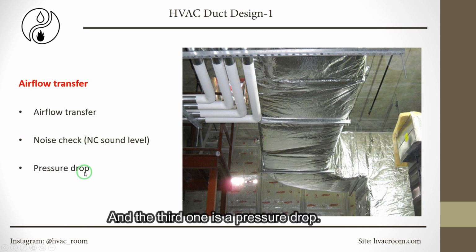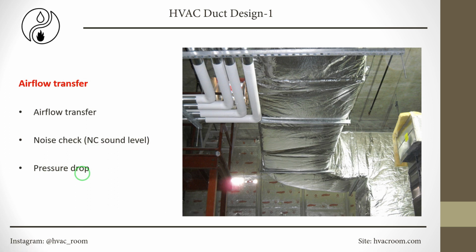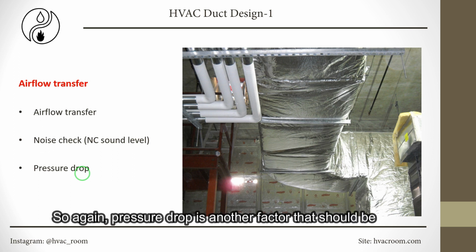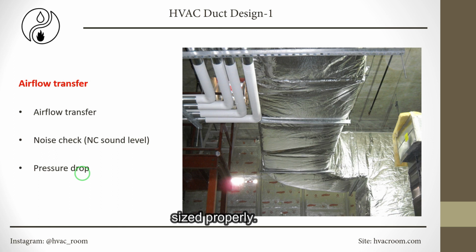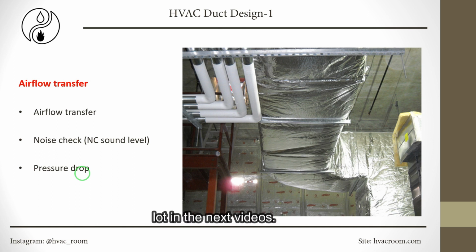And the third one is the pressure drop. Again, if the pressure drop is so high, it's going to increase your current cost. If it's so low, it's going to increase the duct size. So again, the pressure drop is another factor that should be sized properly. We're going to talk about these parameters and factors a lot in the next videos.